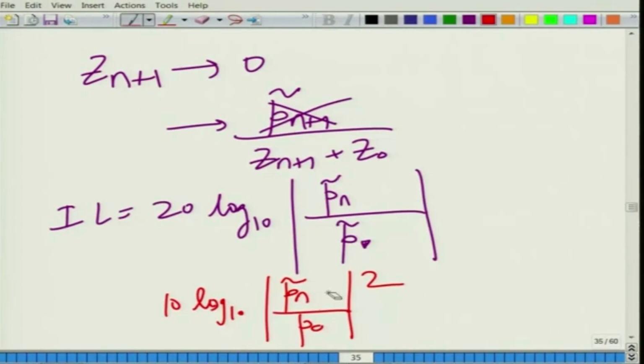Another quantity is the transmission loss, which turns out to be much more difficult to measure experimentally compared to insertion loss, but easier to predict using a set of routines, analytical modeling or numerical FE based modeling and so on. It is best that we talk about TL and possibly about LD, level difference, in the next lecture. So, next is the transmission loss, which we are going to talk about in the next class, that is lecture 2 of week 4. So, stay tuned for that.